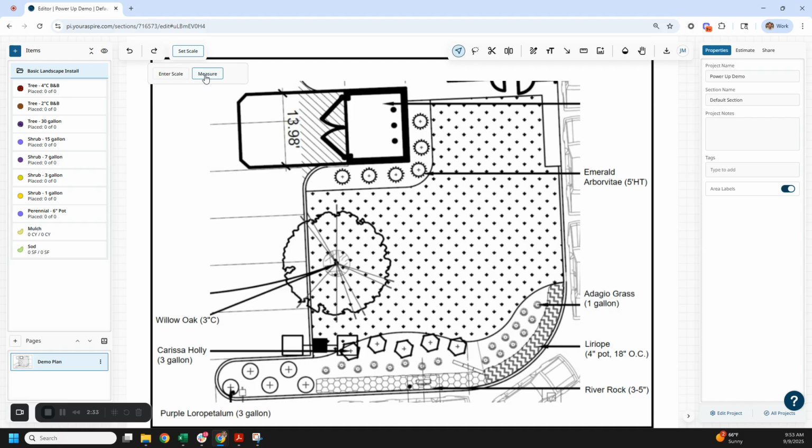For example, the original plan may be something that needed to be a 24 by 36 when it was printed off, but in order to save space, an architect may have exported out a reduced size version of something like 8.5 by 11 and distributed it that way. And so in order for your measurements to be accurate, you want to calibrate the scale.